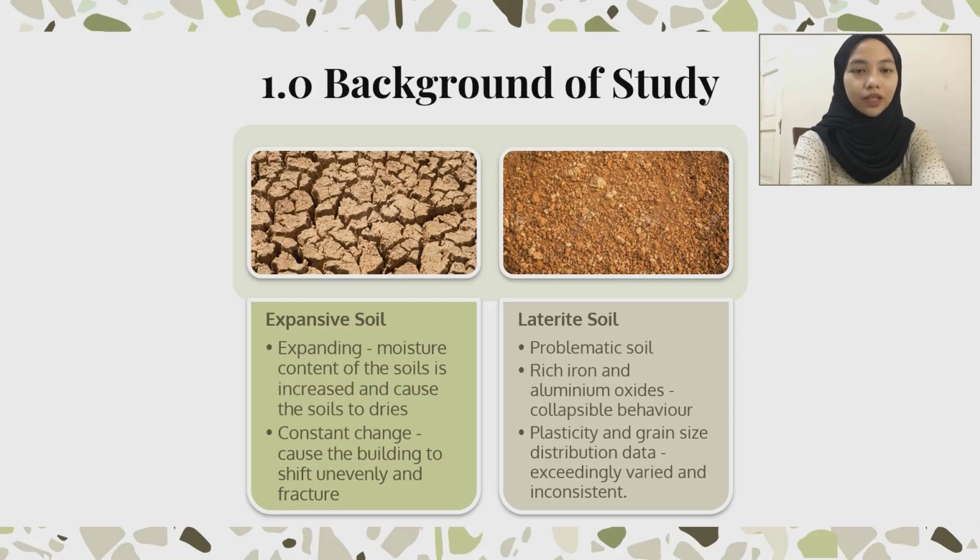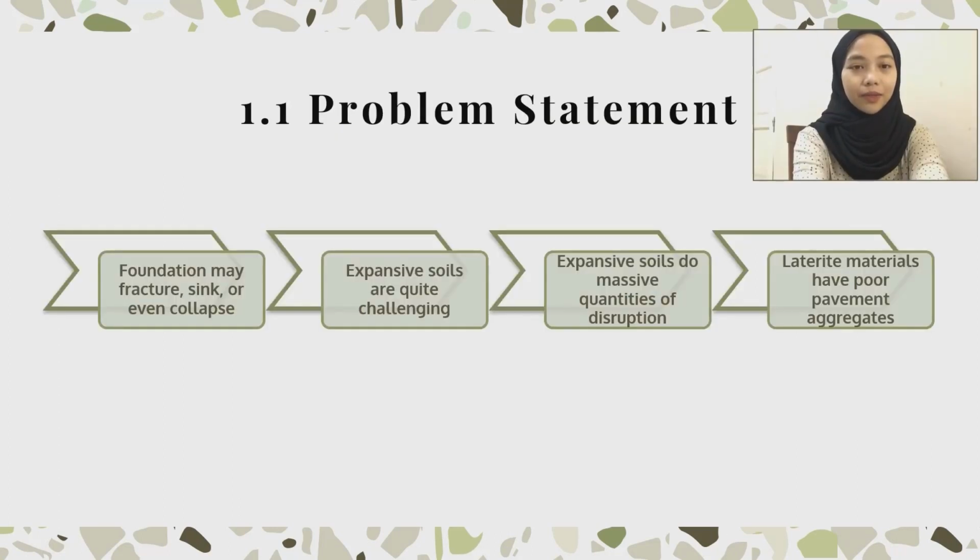It is a severely weathered material which is rich in both iron and aluminium oxides, which means that it has a collapsible behavior. This behavior can lead to cracks and fractures in structures, and also lessen the safety of the structures. Next is the problem statement.